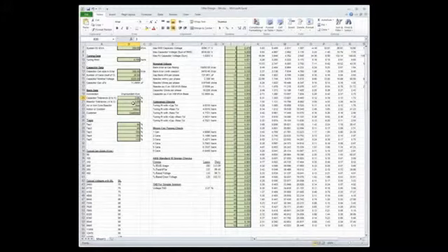And when they're in that positive tolerance range, you'll find that your kVAR is going up significantly. I had a condition where, after designing and having an install on a harmonic filter, during the commissioning effort, we actually pulled capacitor units out of it because, on average, after measurements, I discovered this, the tolerance was about 7% high on the entire bank.